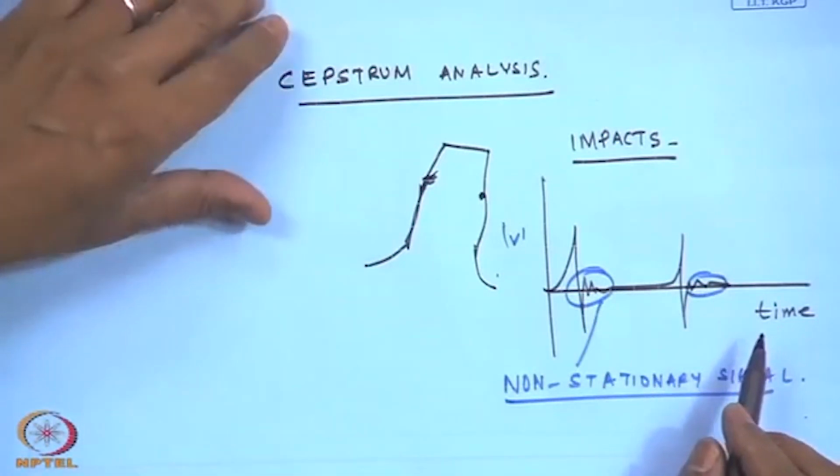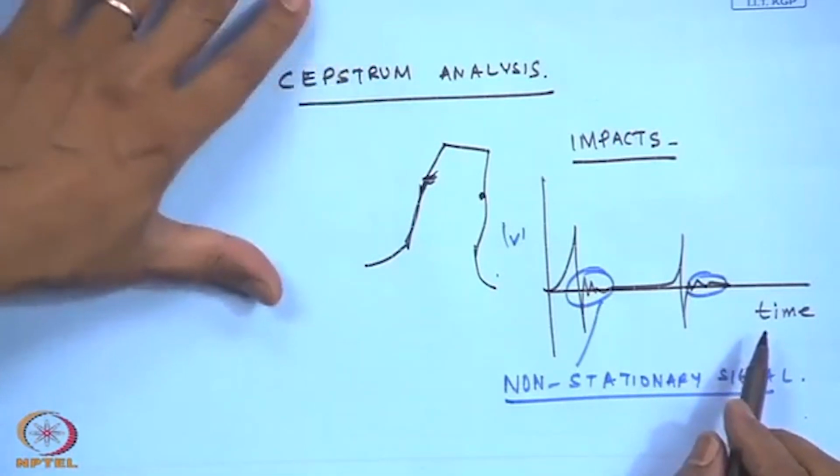So, the fundamental signal processing theorems of stationary signals, wherein the properties of the single ensemble over a given time change is being violated, and thus stationary signal analysis like FFT etc. cannot be done on such signals. So, we have to do signal analysis using non-stationary techniques like the wavelets. Okay.